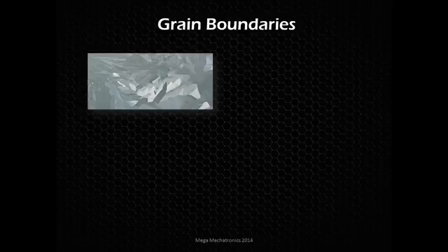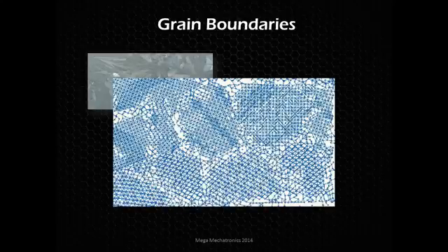And when this happens, when these crystals start forming randomly within the material, they're going to be crystallizing in different orientations to each other. So you see this is an example of a galvanized surface, and that zinc is crystallizing in different orientations, and then we see the light refracting off of that in different ways, and then we can easily make out the grain boundaries.